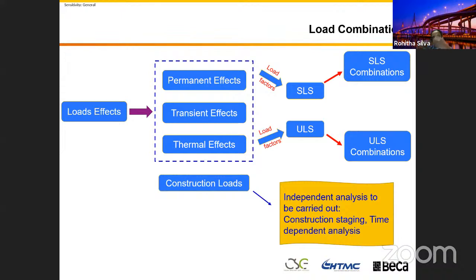That will produce, depending on the bridge articulation or the substructure-superstructure connection, a different moment in the bridge. Another thing, please remember that when we build bridge superstructures, for example I-girder bridges or even continuous span box girder bridges, sometimes we cast in stages. That creates a complex creep and strain system in the bridge that creates additional moment. We can do the analysis using software.